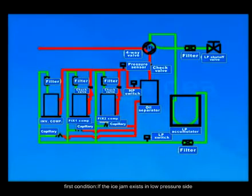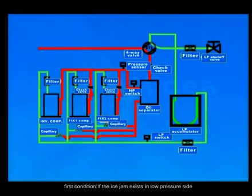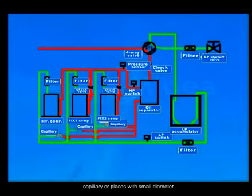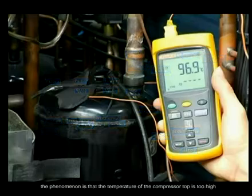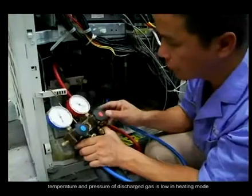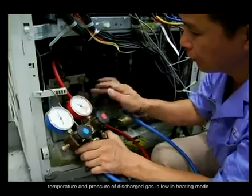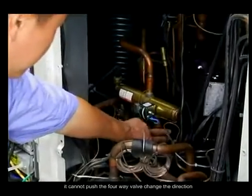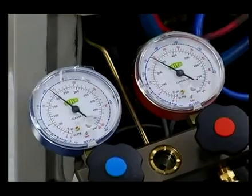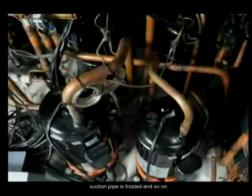First condition. If the ice jam exists in the low pressure side, it is very possible that the ice jam exists in the filter of the suction pipe, capillary, or places with small diameter. The phenomenon is that the temperature of the compressor top is too high. Temperature and pressure of discharged gas is low. In heating mode, it cannot push the four-way valve to change the direction. High and low pressure of cutoff valve is similar. Suction pipe is frosted, and so on.